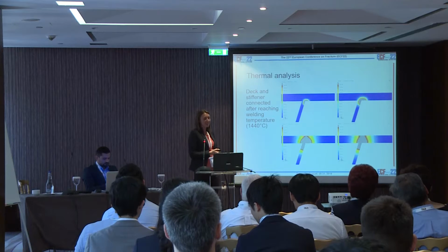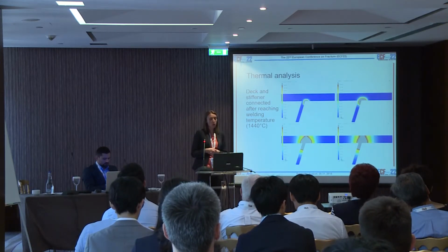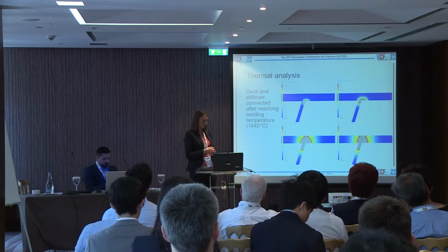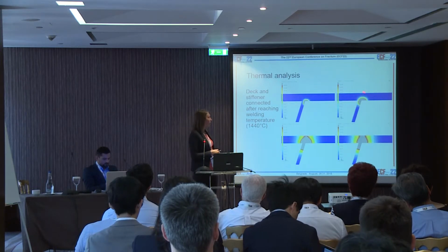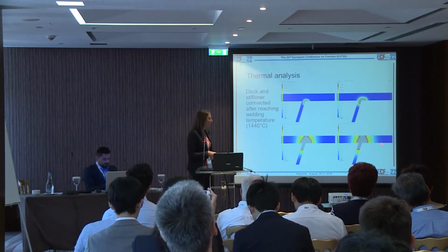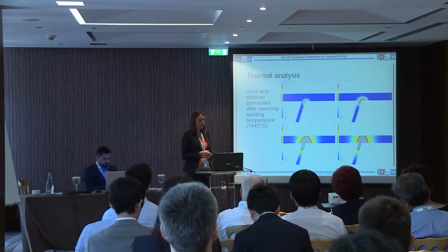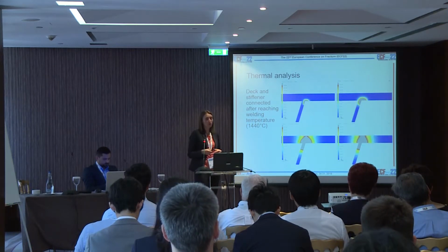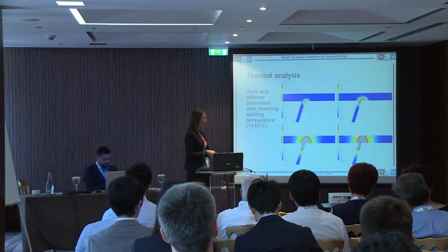During the thermal analysis, the mesh of the deck and the stiffener are not yet connected. Only after passage of the welding torch, this is after the temperature of 1440 degrees Celsius is reached. This is here. You can see that the weld melt-through is obtained and that we have a good connection of the deck plate and the stiffener. And only after this time in the model, the meshes will also be connected.